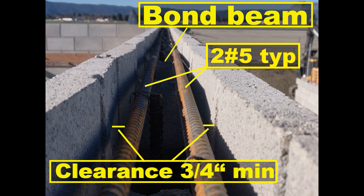Provide precast concrete trim, lintels, copings, splash blocks and sills that are factory-made units in a plant regularly engaged in producing precast concrete units. Unless otherwise indicated, provide precast concrete with minimum 4,000 psi compressive strength, using 1/2 inch to 3/4 inch nominal size coarse aggregate, and with reinforcement required for handling of the units. Maintain minimum clearance of 3/4 inch between reinforcement and faces of units.